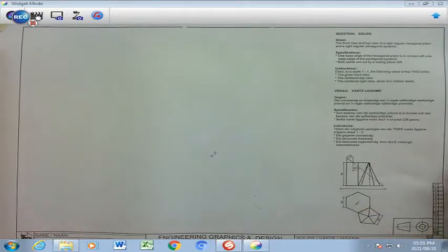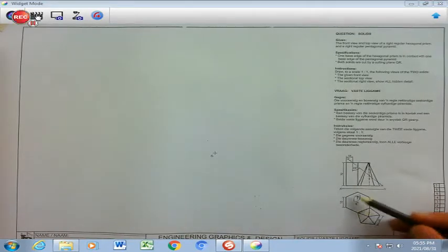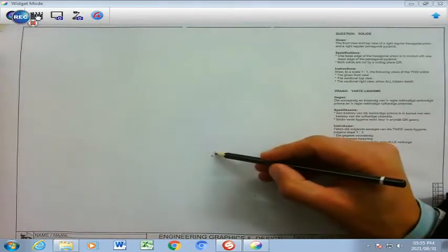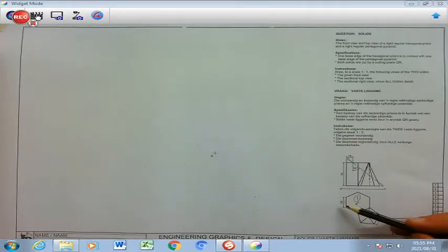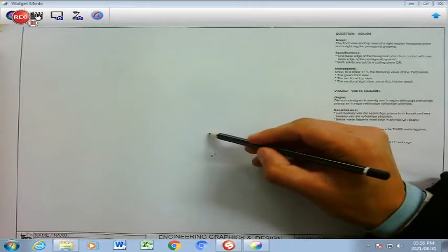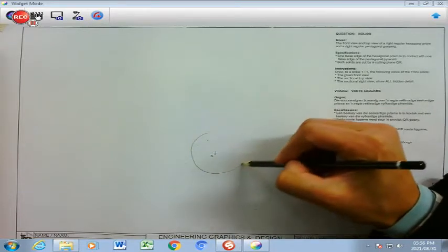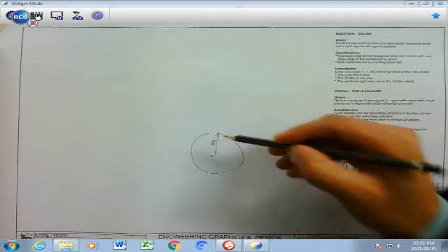Now, just before we go into our formal drawings using our set squares and our T-square, let me explain to you the different steps. So we're going to start with step number 1, where you are going to draw the shape of your hexagonal prism around the reference point S. So you will find that there's a 32 length, which basically means that you can draw a circle with a radius of 32. So your radius here is going to be 32, which is from here to there, 32.